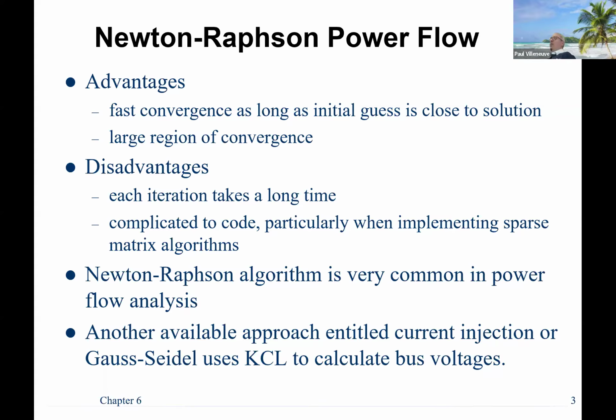And so we usually assume a fixed starting voltage, but if you were going to do more of the ISO New England like system planner work, they actually have to look at a lot more load flows. And so they have to do their runs and it just takes a long time. But it converges, right? We've seen 4 iterations and you were down to less than micro in terms of differences. So fast convergence, and they converge pretty well as long as your initial guesses are fairly reasonable and you haven't made any mistakes, right? Like you actually put the 4 multiplier, you didn't forget it.